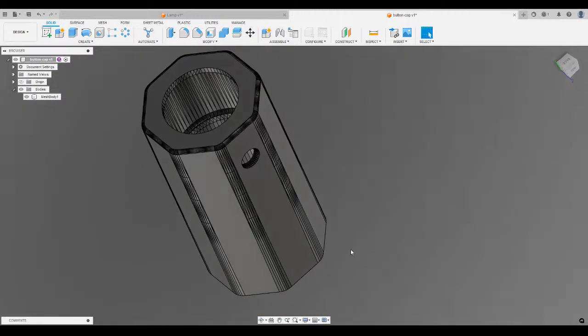This shape was probably defined with a few hundred, maybe a few thousand triangles at the most. And prismatic didn't work. I don't know if I've ever gotten it to work. Usually the STLs you get for 3D printing files are so large, with so many triangles, that prismatic's just not gonna work, because it's a lot for it to try to figure out.